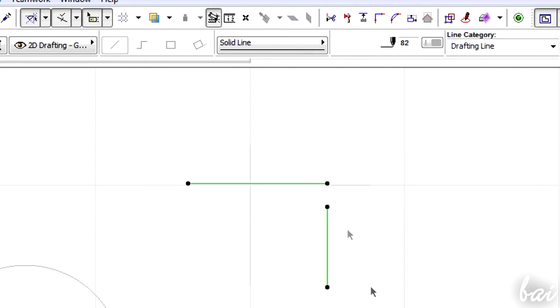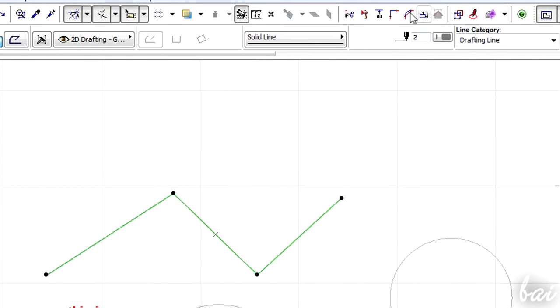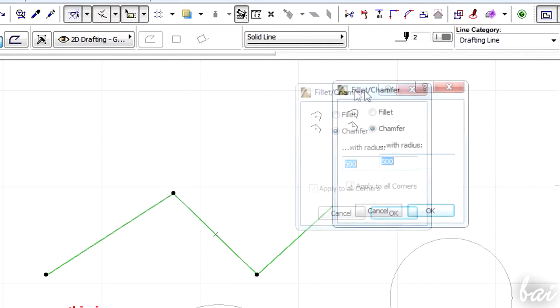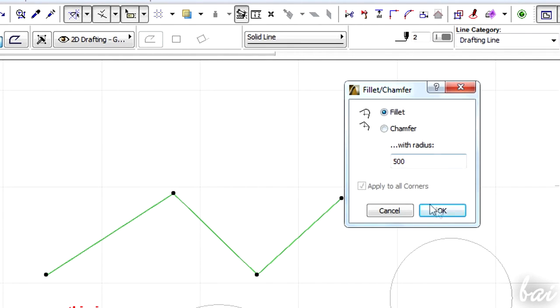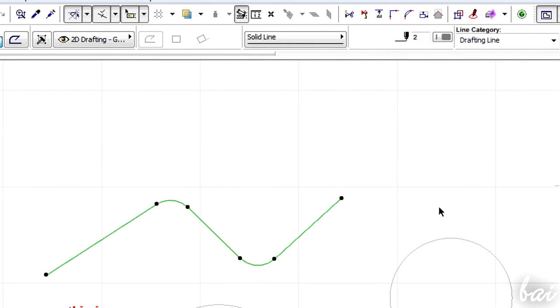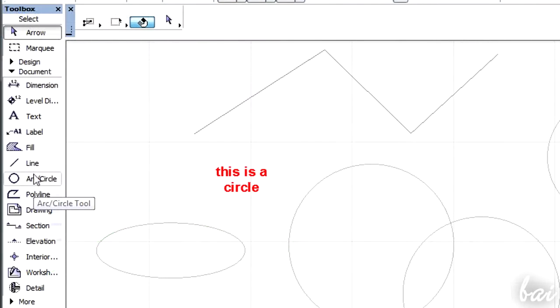Intersect is used to connect objects together, especially to build up angles. Just make sure to have the objects selected first, before using the button. Fillet chamfer is used to get rid of harsh vertices. There are many other ways to edit your object. Experience will guide you through.